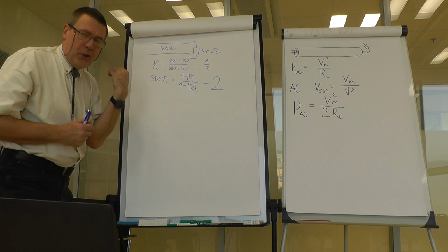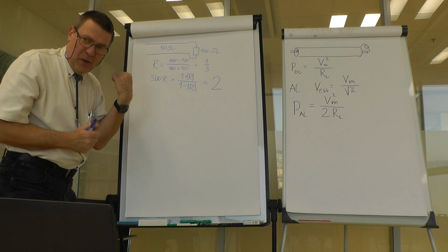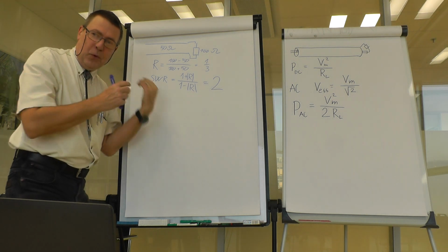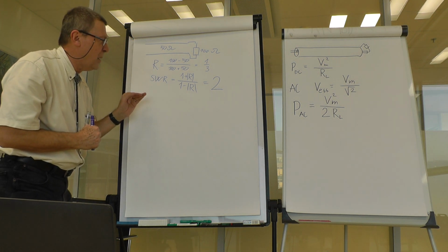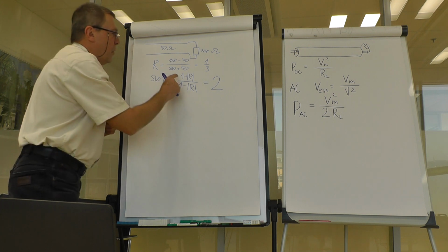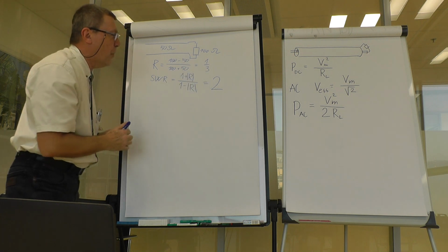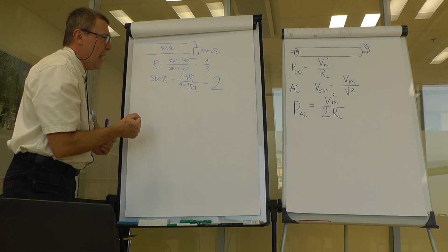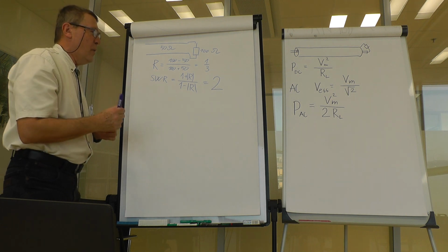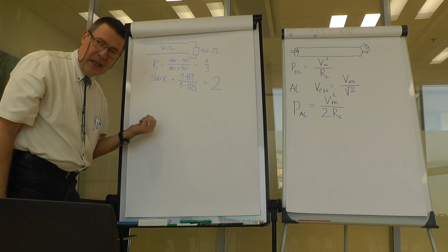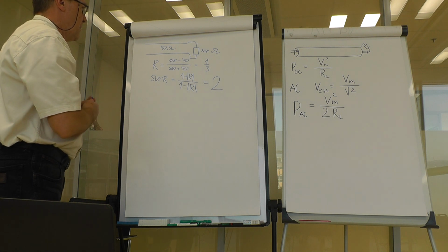So we would overshoot the maximum voltage allowed on this line, and it would break down. So we would have to decrease the input power. How much? Well, 1 plus 1/3 times the input voltage, or 4/3 of the input voltage, should be equivalent to the maximum. So we would be only allowed to put there 3/4 of the original voltage.